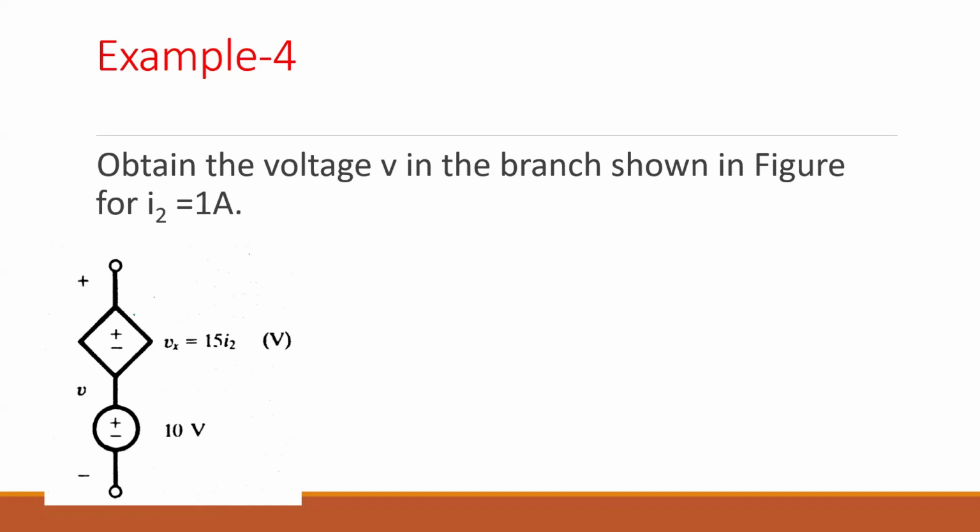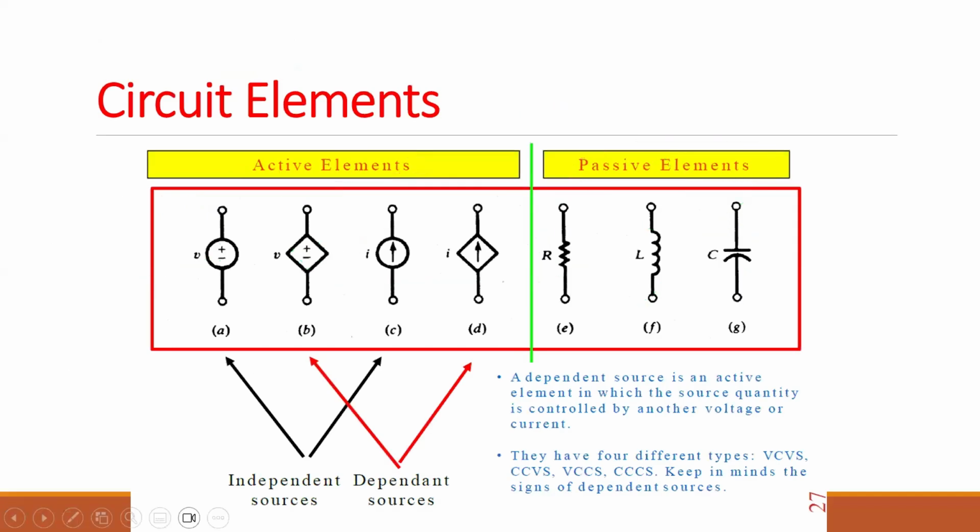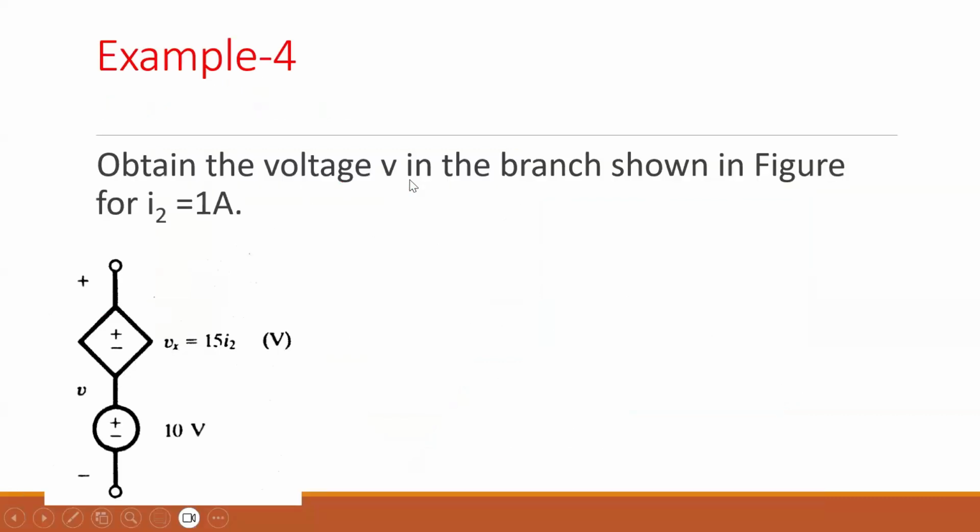They are voltage. Why do we call them voltage? I told you, you always need to look at what you have. Whenever you have a positive and a negative side, that is voltage, and when you have an arrow, that is the current source. So current is an arrow, voltage is a positive and negative. So they are voltage sources.